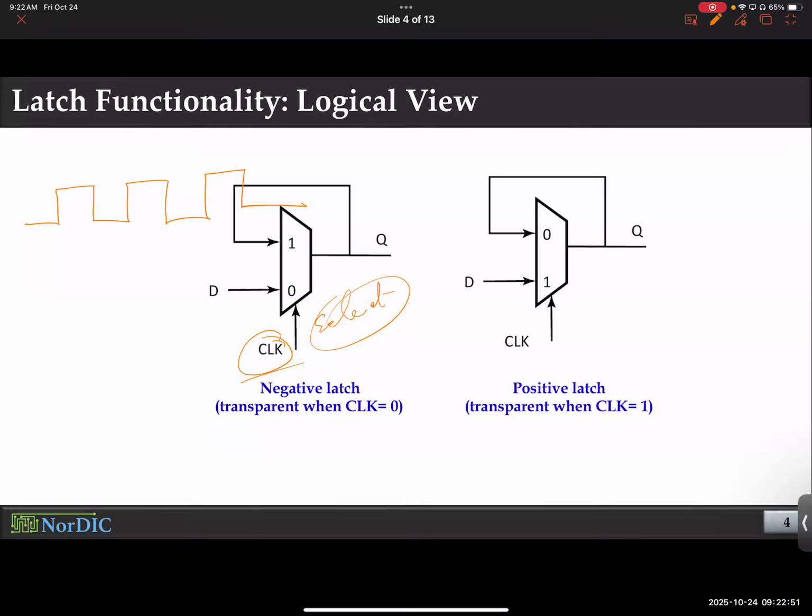And it is a very simple mux, folks. As you see, it's a 2-to-1 mux. It is choosing between whether to send the input to the output or whether to keep the output as was. Does that make sense? So, or unchanged. So it is taking a decision. Should I keep the output unchanged or should I send the input to the output? This is the only decision it is making. So it is a super simple mux, the easiest it can be.